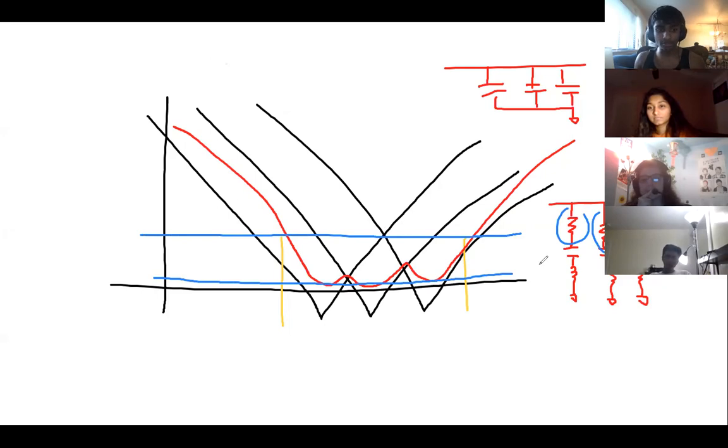So you look at the ESR value in your capacitor data sheet, and you're like, wow, this is huge, I don't want that. Some capacitors are better about having lower ESR, and some of them have giant ESRs. It really depends on the type. And when we get into that, you get into what types of capacitors we should use. Should we use aluminum electrolytic? Should we use tantalum electrolytic? Should we use ceramic? Each of those has its own pros and cons.